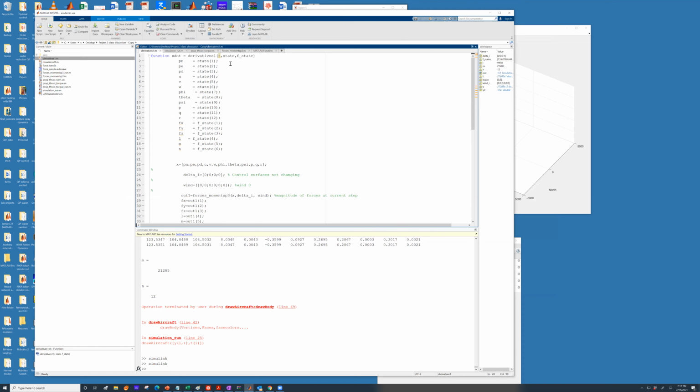If you are downloading the new MATLAB, I recommend you take all your old work, make a copy and save it in Dropbox or some other folder, and then download MATLAB. Because if all your previous work is inside the default MATLAB directory and you uninstall the original MATLAB, it will ask you if you want to get rid of .m files. So if you don't want to risk that, I would recommend you save all the files in a separate folder.